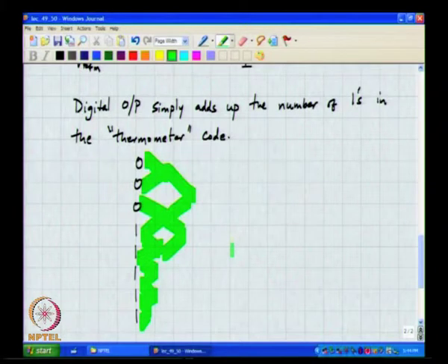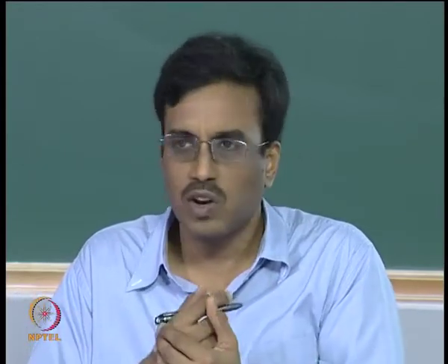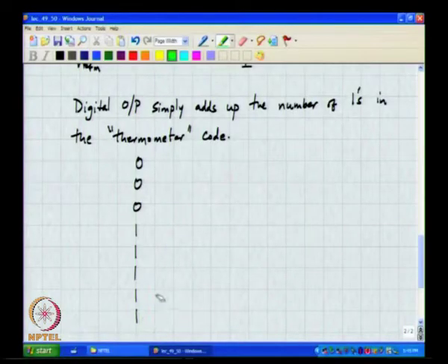So, you get some kind of tree structure, where the depth of this tree depends on log n, where n is the number of numbers you wish to add. I think this is called a Wallace tree adder, right. Okay. So, this is something which is also done in flash converters, especially those used in a delta sigma loop.